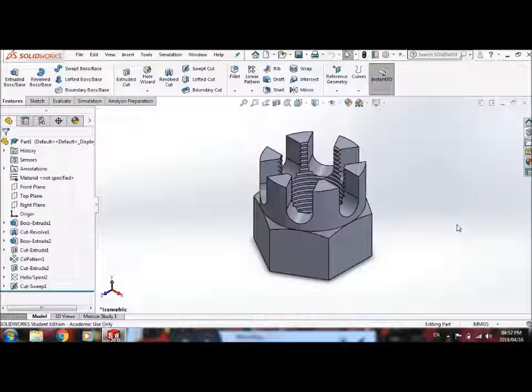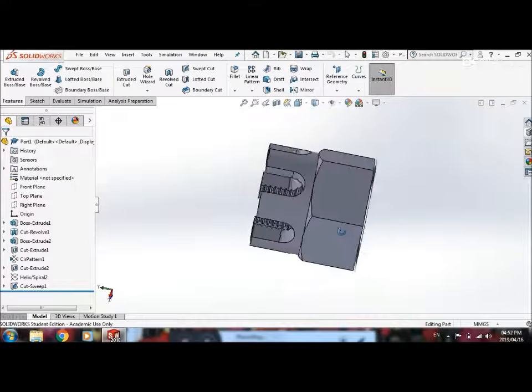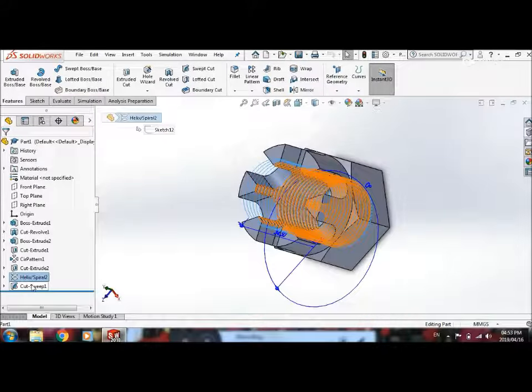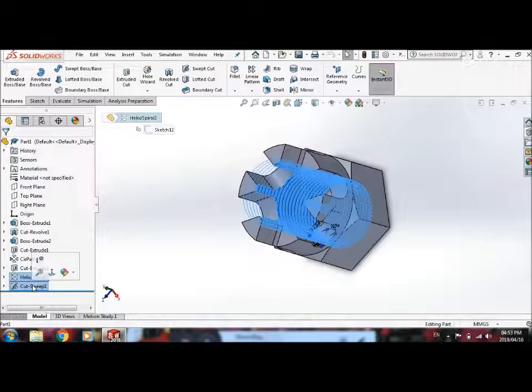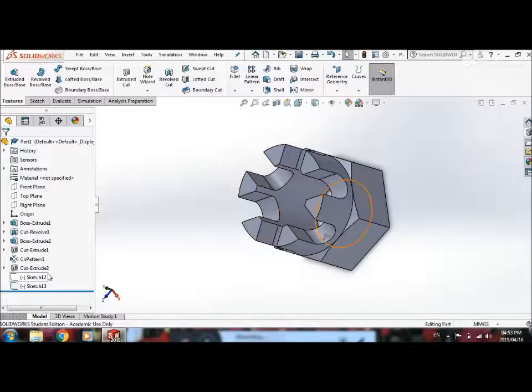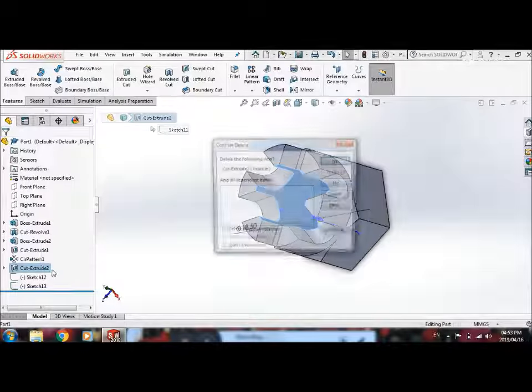Right, that's a good question. If I want to use these things in an assembly drawing, then obviously it's not necessary for me to draw in the whole spiral every time. Usually these spiral cutouts really destroy your computer's processing ability because the graphics has to solve each of those little lines the whole time. So this is the detailed way to do it, but it's actually not the correct way if you're wanting to use them. So I'm just going to delete my threading that I cut there and delete that hole.